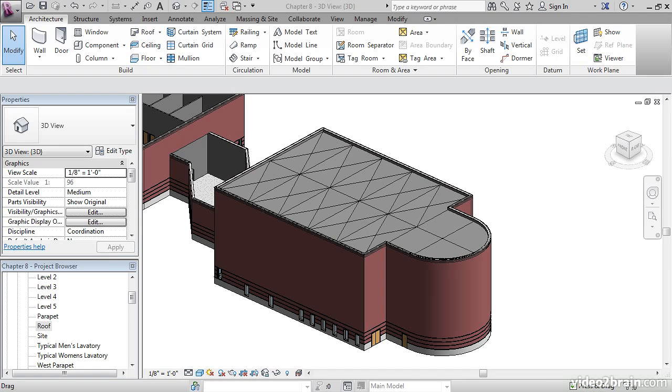The objective of this exercise is to lay out a roof using reference planes. Then we're going to add split lines to form the areas of containment, the high points. Then we're going to add points down 3 inches from the surface, the low points. We'll leave the actual drains to the plumbing engineer. He needs to put them where we're showing them on our plan though. Open the file you've been working on, or open the file called Chapter 8 and follow along.